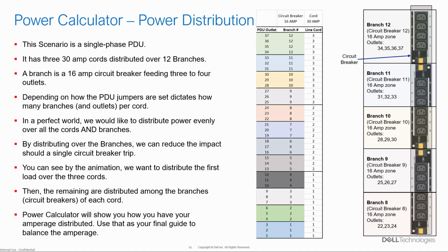So that entire node is consuming 10 amps total, but only 5 amps from the left and 5 amps from the right. Now, what happens if a power supply fails or the PDU fails? What that node will do is push all that current to the remaining power supply or PDU. So in this case, if this was a 16 amp breaker, let's say I only want 7 amps here in a normal state, because if the other side fails, it's going to get doubled, so it'll go up to 15.